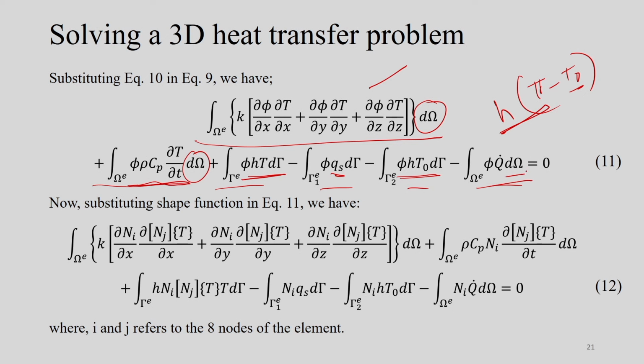So, this is the volumetric term. Finally, combining this using the discretized Galerkin weighted residual technique, if the weighting function is replaced by the shape function, so that the weighting function is equal to the shape function, then we can reach this particular expression. That total derivation can be explained somewhere else, but the point here is that we can utilize the shape function to form one elemental matrix.